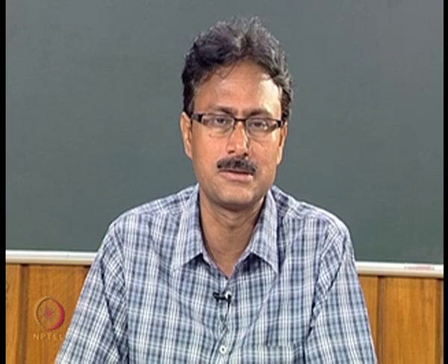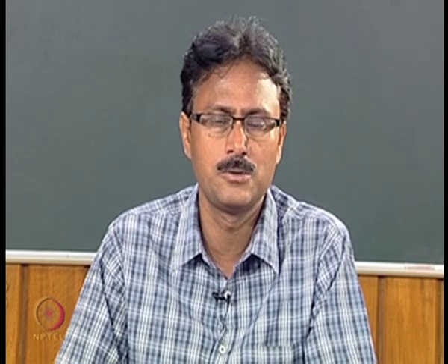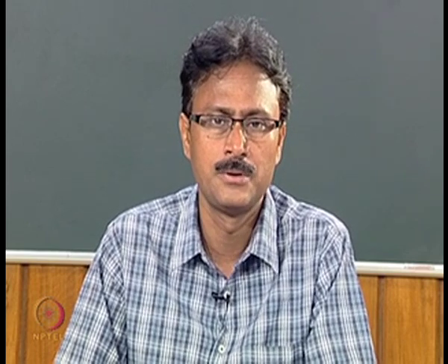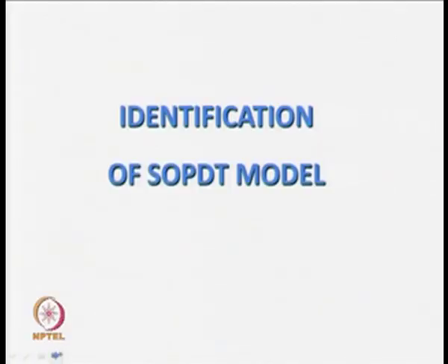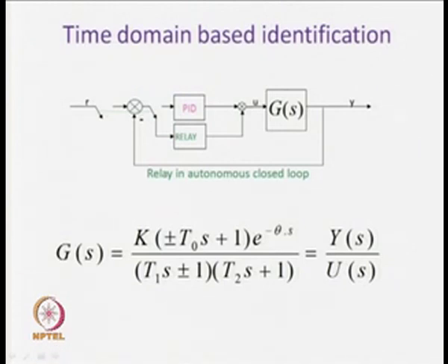In this lecture, we shall consider a bit higher level transfer function model, where the transfer function will include a right half zero or left half zero apart from two poles. The poles can also be right half poles. So, we will see first the structure of the relay test we shall employ for obtaining sustained oscillatory output. Now, the PID controller will be detached first. A relay will be connected to induce sustained oscillatory output.